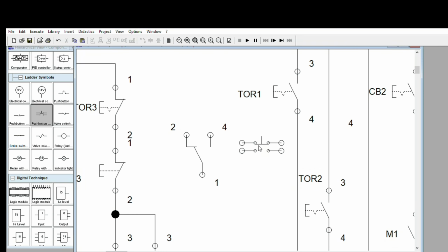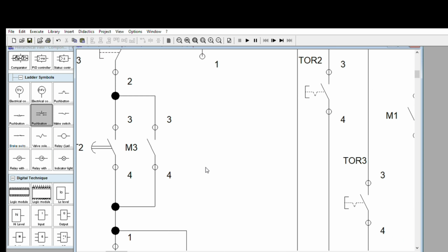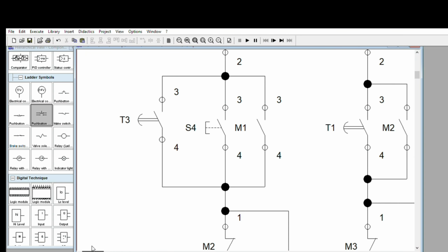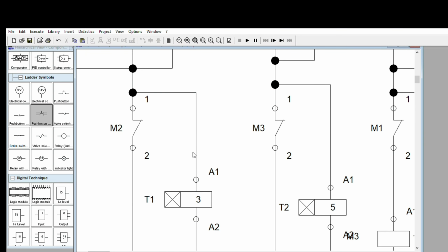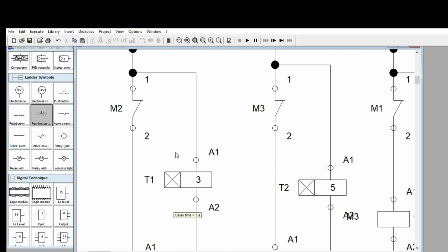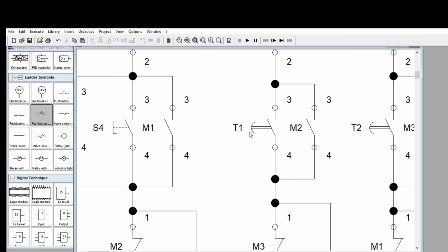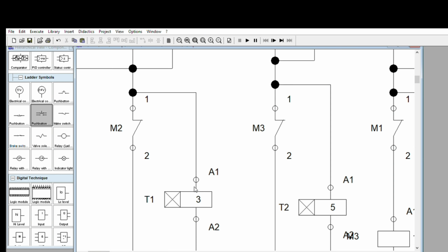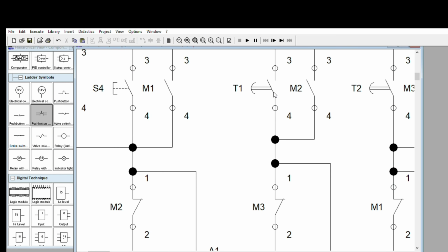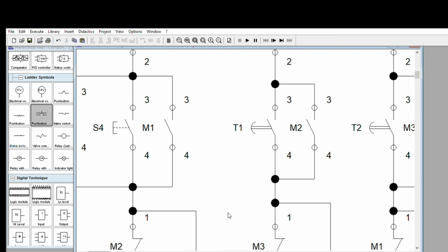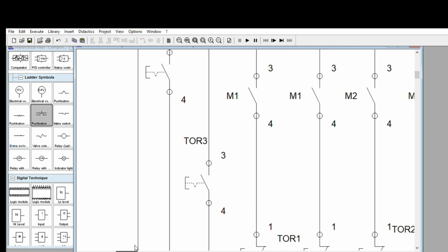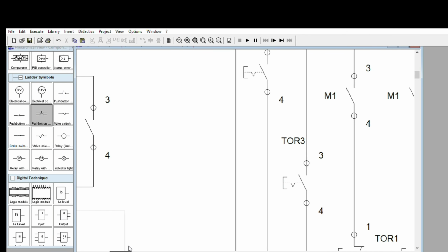So this one will open first, and it will take milliseconds for that contact to reach the other one. So this one is open first. If that one opens first, both supplies are cut off. So usually the timer contacts are placed here. When you turn off the circuit, the double interlock system is better. So it's better to have the double interlock here, the timer with a C contact here and an O contact. There is a millisecond difference because they are electromechanical contacts, dependent on the transition.